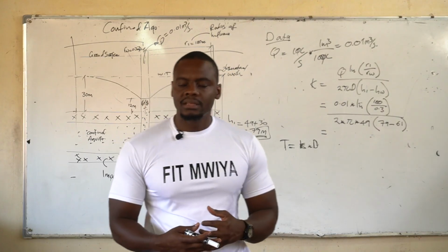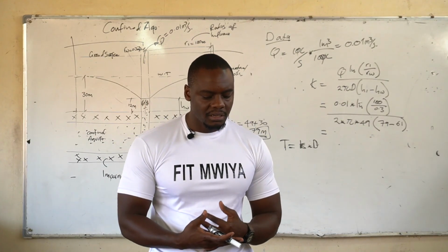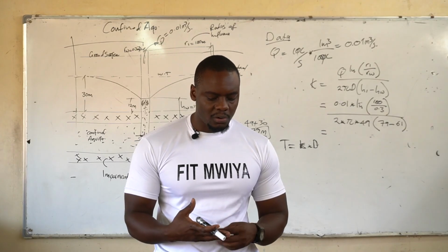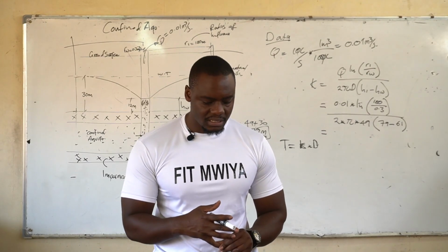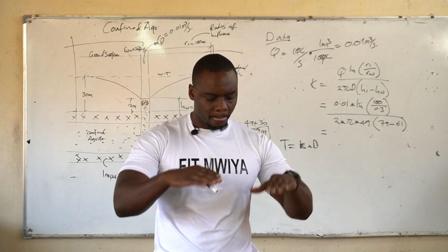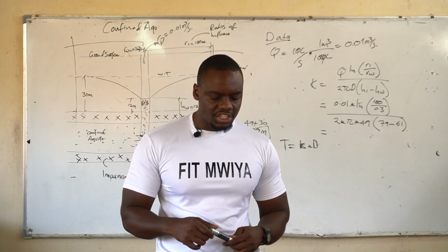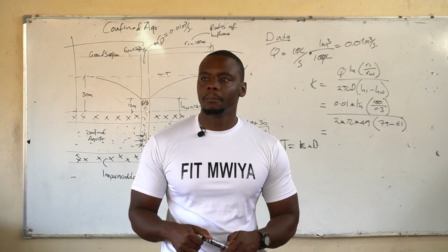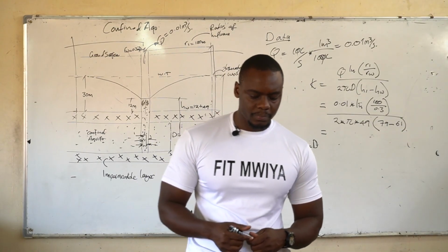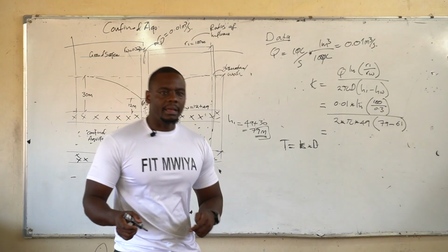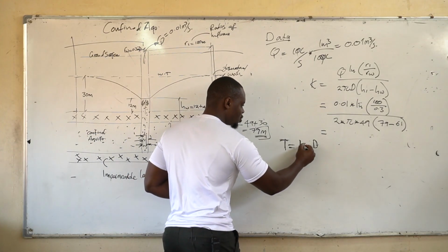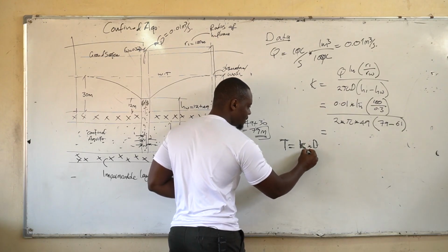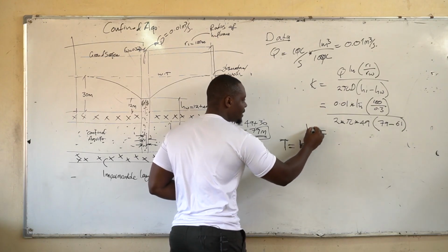So I said the transmissivity, capital T, of an aquifer is a measure of how much water can be transmitted horizontally, comma, such as to a pumping well. And this is how you find it. So it's just T is equal to K, and the K is the one that you're finding here.